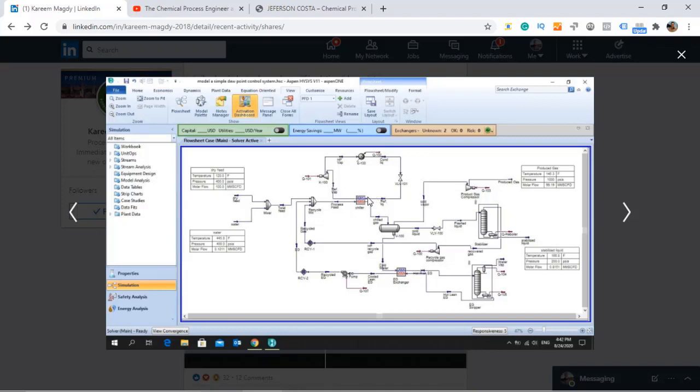So how it is done is based on the temperature at the outlet of the heat exchanger. If my closed loop has any kind of trouble, for instance, I have inefficiency in the compressor and my temperature in the closed loop increases, I will also increase the outlet gas stream temperature at the heat exchanger, and because of that I will have a higher dew point, and I need to fix the closed loop in order to get my dew point at the specification again.